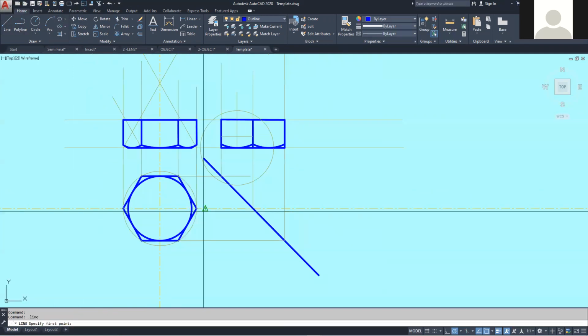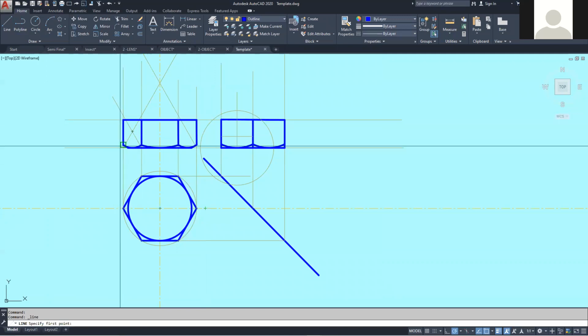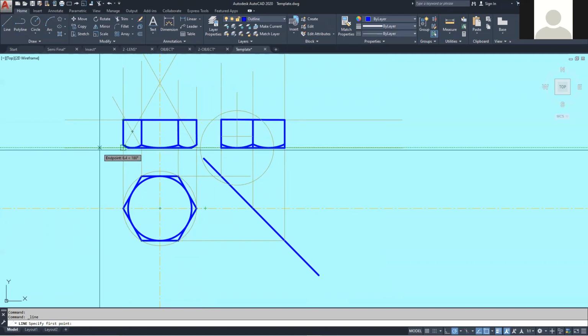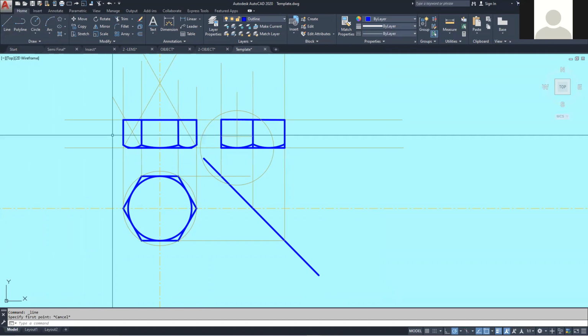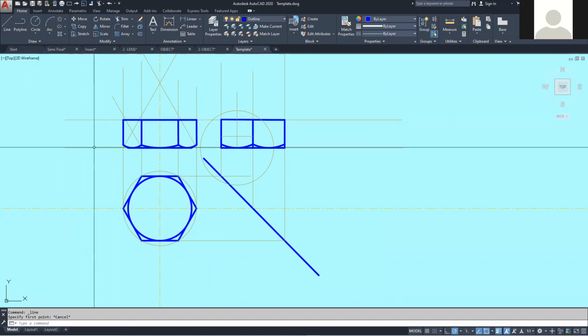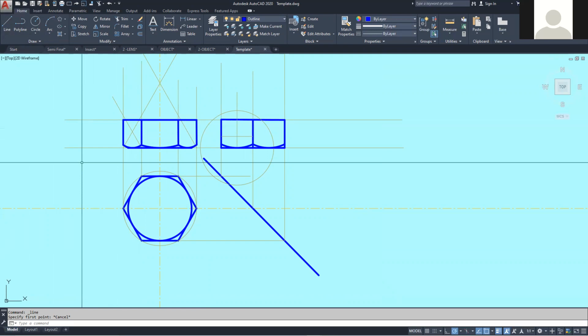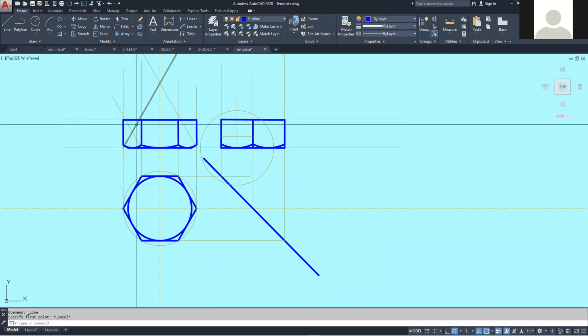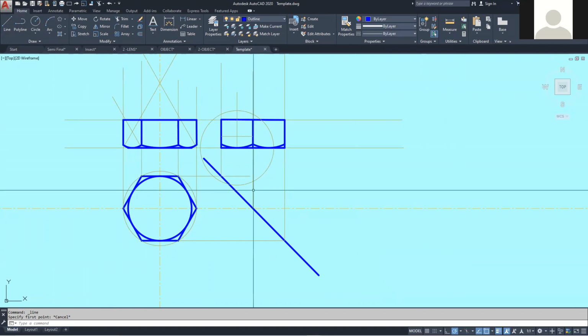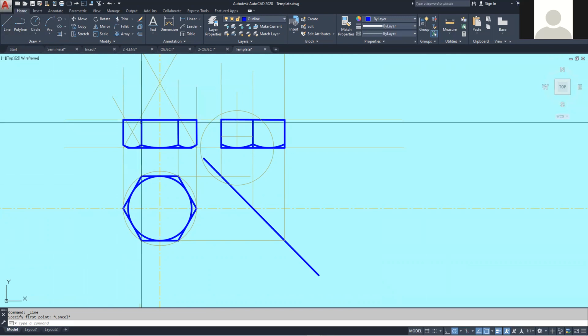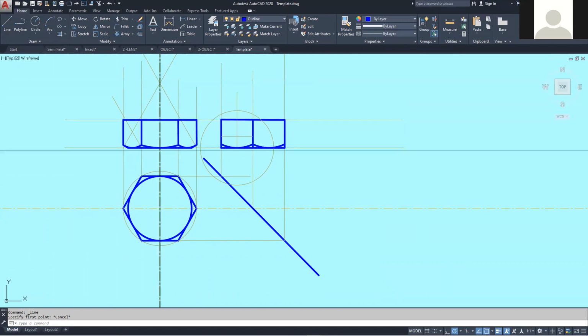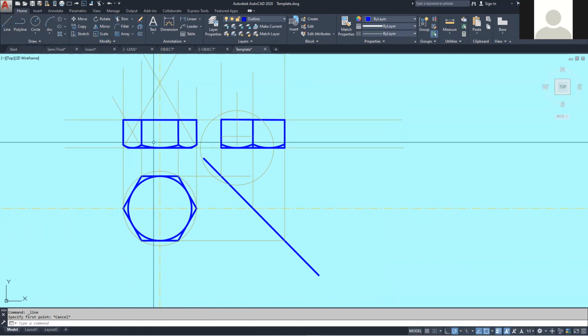Now, for drawing purposes, the height of the bolt is 3/4 of M, which is 3/4 of 10, which is 7.5. So from here to here, 7.5. You then use your knowledge of orthographic projection to carry up your lines. From each corner, you go 60 degrees where it meets here, the center line. From the center here to here is where you draw this curve.